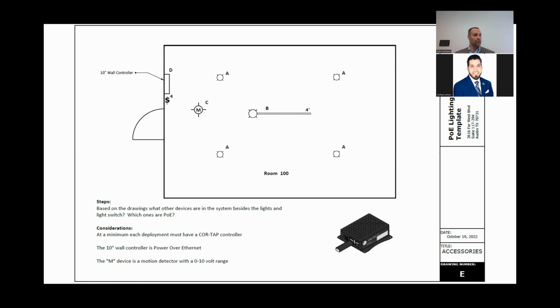Yeah, I mean, you could programmably assign them, even if they're used somewhere else. I can get them to the closest link that has ports. Yes. So let's say you had like an 8-button switch. What you would do then is you would take 4 of those inputs to one link, and you could take the 4 other buttons to another link, and then you'll be able to, in software, associate those buttons with whatever you want. That's the great thing about PoE. You don't have to feel like just because I'm not wired to the same link, I can't make an association. You can make all those associations you want in the software.